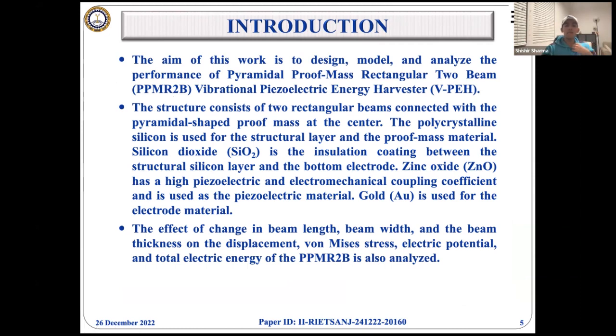And so the basic design for our project is we took a pyramidal proof mass and 2 rectangular beams connected to each other. On the beams and proof mass, the structure is made of polycrystalline silicon. And we coated a thin insulation layer of SiO2, which is a very cheap material. And then we put a layer of piezoelectric